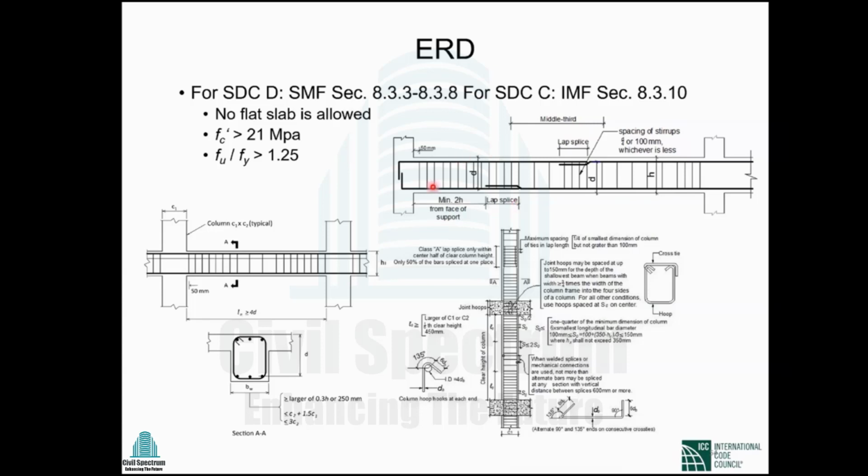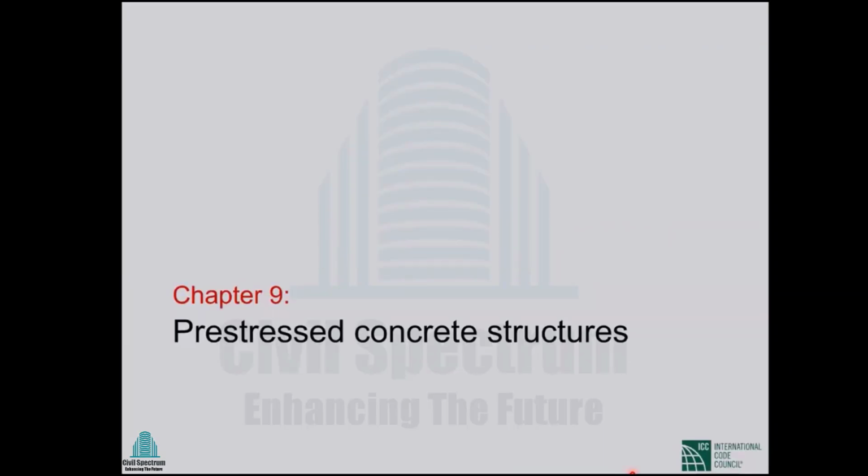So, and the details: the stirrup spacing, tie spacing, ties within joint, hook, angle of hook, length of hook, width-depth ratio of beams, and width of beam as compared to the width of the column, all these ratios, and there are many other requirements that you have to follow if you want to construct a D type building. So these will be covered in detail by Dr. Ghosh. Let me go forward.